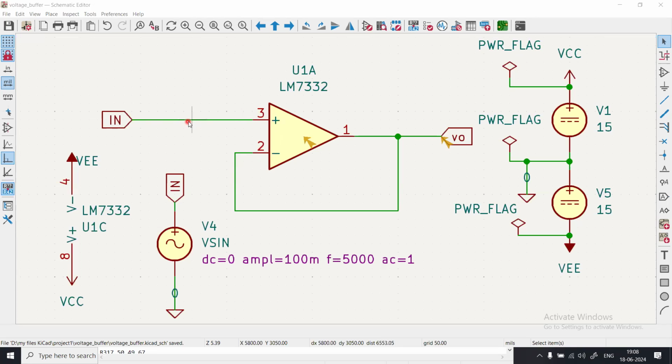So if you have 1 volt here, there will be 1 volt here. There will be no difference between the input voltages, and that's why, as we have seen multiple times, the amplifier gain tends to infinity, because if the gain tends to infinity, the difference tends to be 0 between the two inputs of the amplifier. So the input at the positive pin comes at the negative pin.